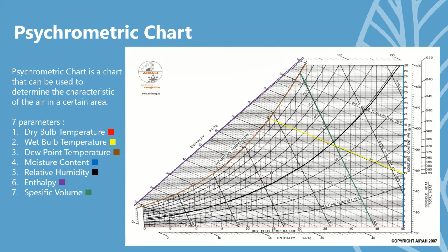One thing that you need to know, if the dry bulb temperature and wet bulb temperature values are equal, it can be confirmed that the dew point temperature is at the same temperature as dry bulb temperature and wet bulb temperature.